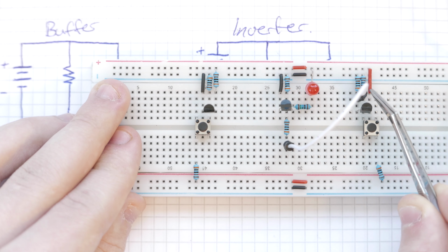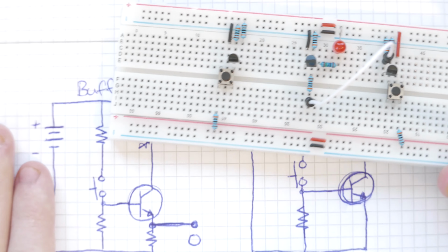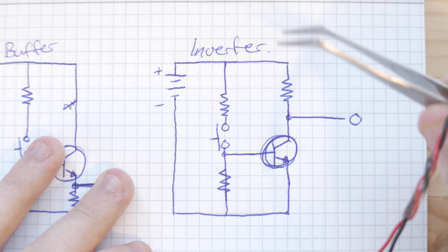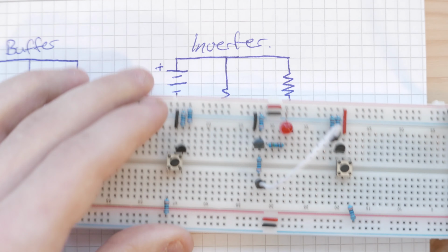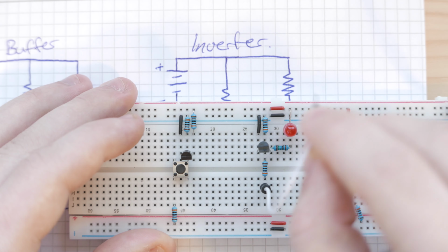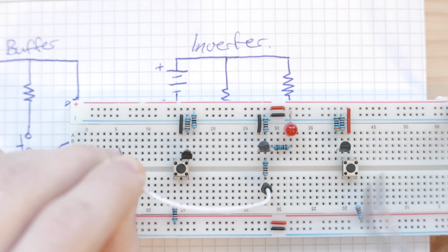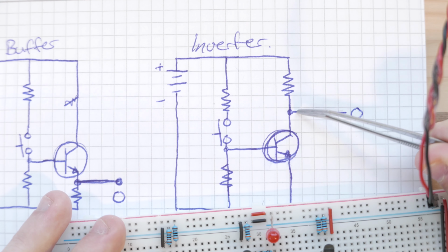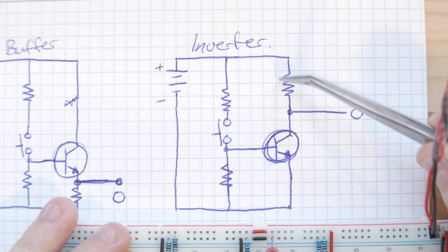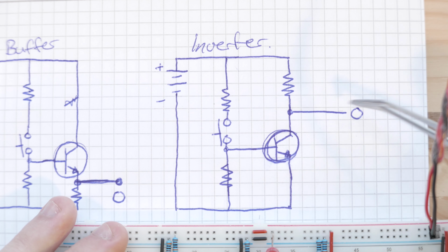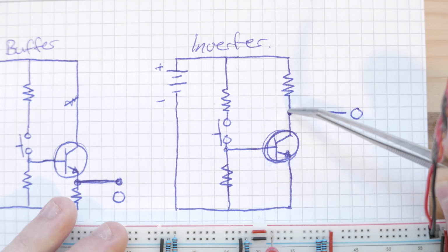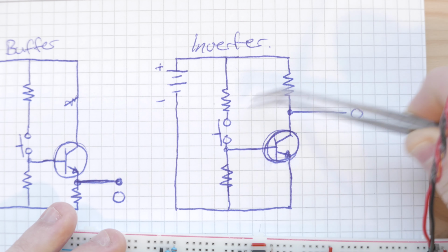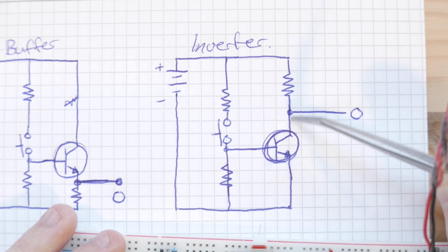It looks very similar to this one, but if we scoot over here, let's just have a look at this circuit first. So, just try to imagine in your head what happens when I take this white cable and attach it to the output of this circuit. Now, you'll see this output is immediately connected to 5 volts, right? And what happens here is that we actually have a 5 volt potential at this node. Now, these are all just 3K resistors as well, but it's not really important. You'll see that the potential here is 5 volts.